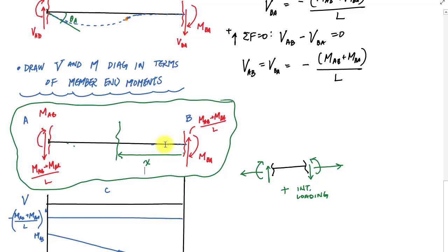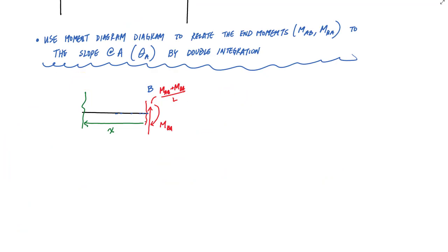And I will take this drawing and I'll bring it down, this cut out. And here is my free body diagram for that cut between member A, B. I'll have some internal moment that I'm trying to solve for. I'll call that M1. And then there's a shear here. I'll call that V1. All right. And those are my symbols for the moment and shear functions. To get that moment function, I can just sum moments about the cut.